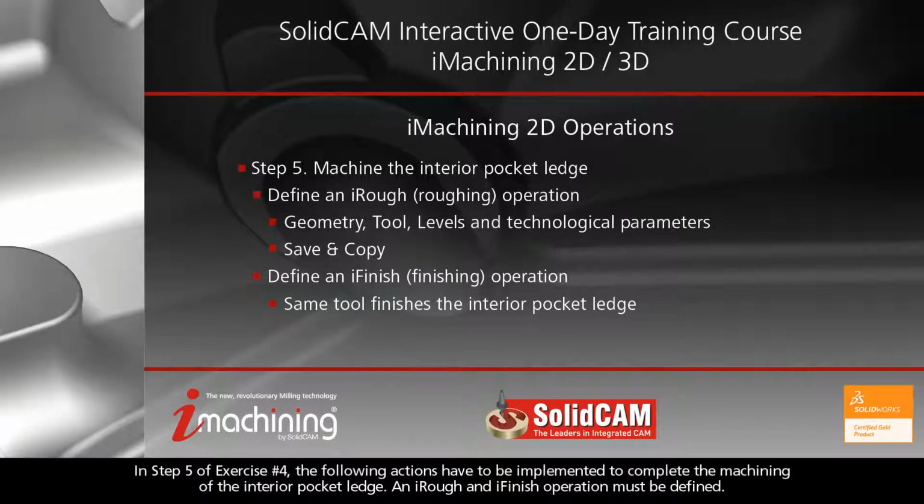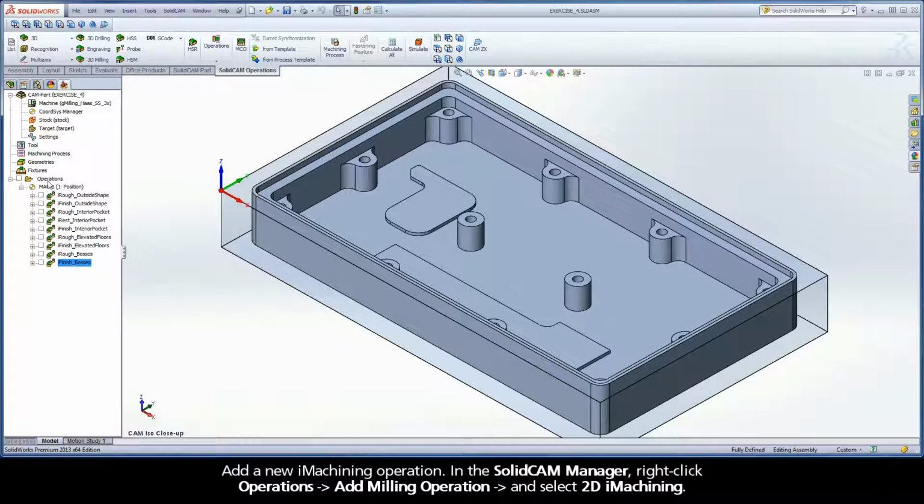In step 5 of exercise number 4, the following actions have to be implemented to complete the machining of the interior pocket ledge. An iRough and iFinish operation must be defined. Add a new iMachining operation.